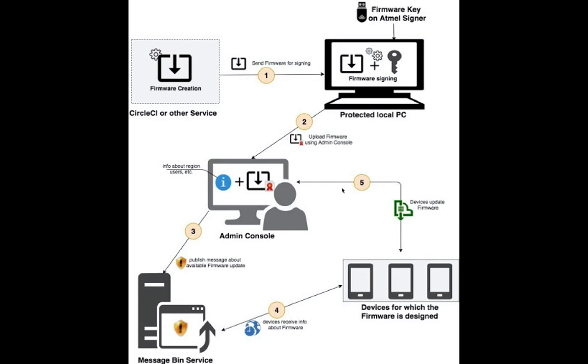Each device downloads its own firmware, stores it in some space in flash, uncompresses it, etc. It verifies signatures and informs the system about new firmware. After that, the logic of your device will make a decision about the most suitable, most convenient time to reboot your device and install it.